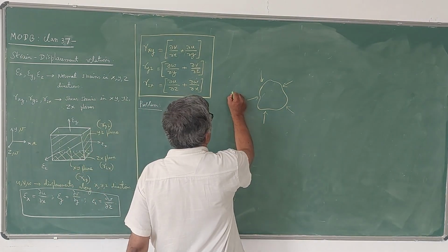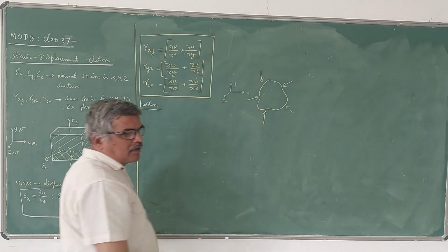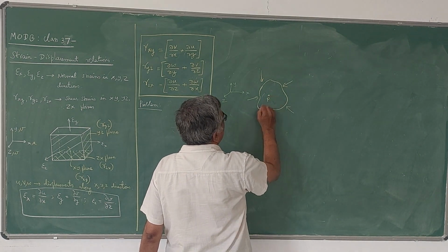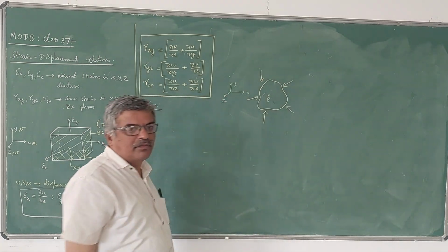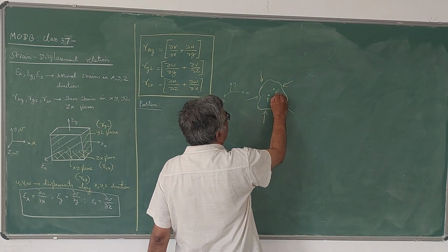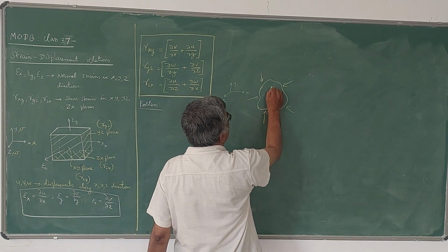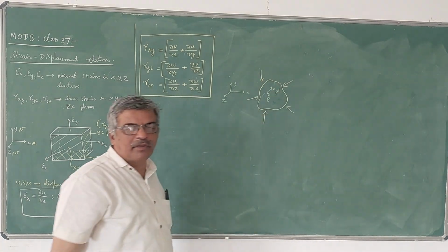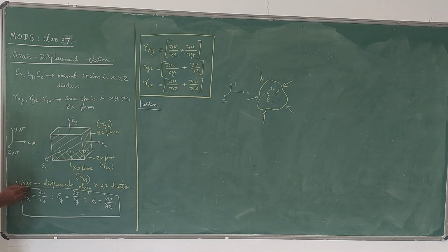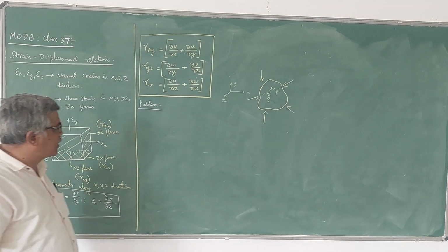So you will be having three directions, x, y, z directions in general. Whenever some load is applied at some point, let us say here P is the point, at this point we will have some displacement. It may shift to some other point due to the application of the external forces. This is known as the displacement. The displacement can be measured in all the three directions, x, y, z directions. So I am going to take those displacements as u, v, w. So u, v, w are displacements along x, y, z directions of that particular point.